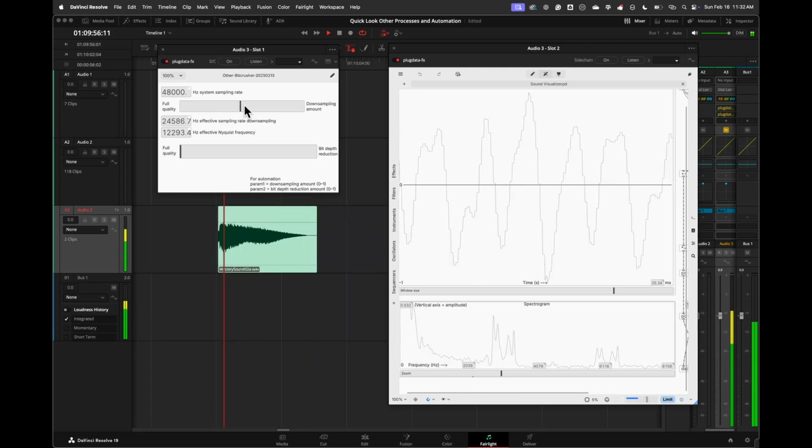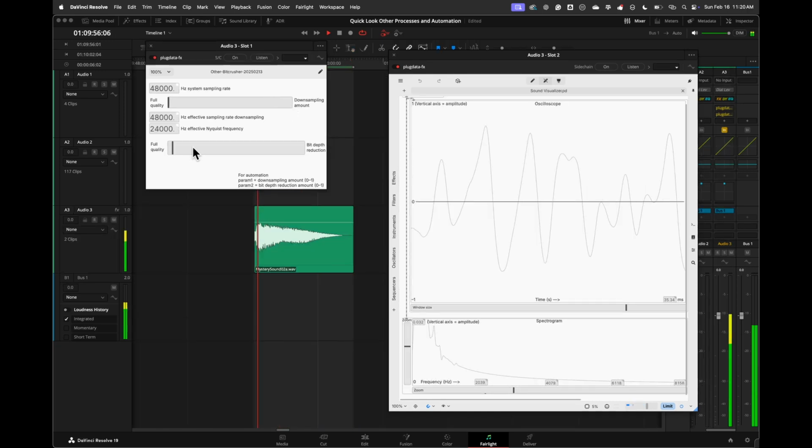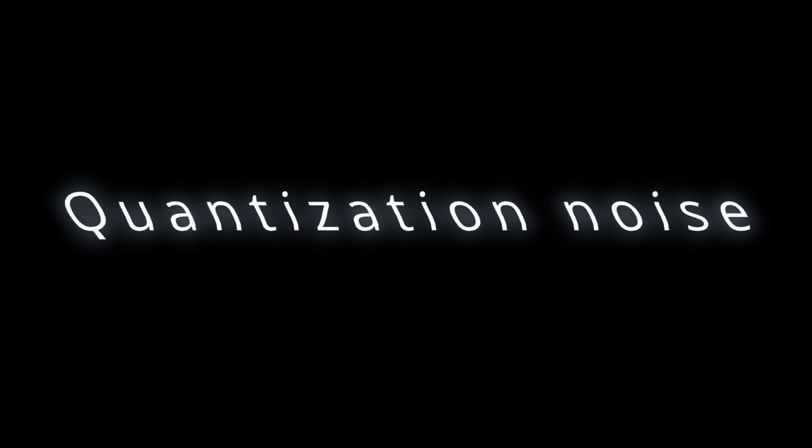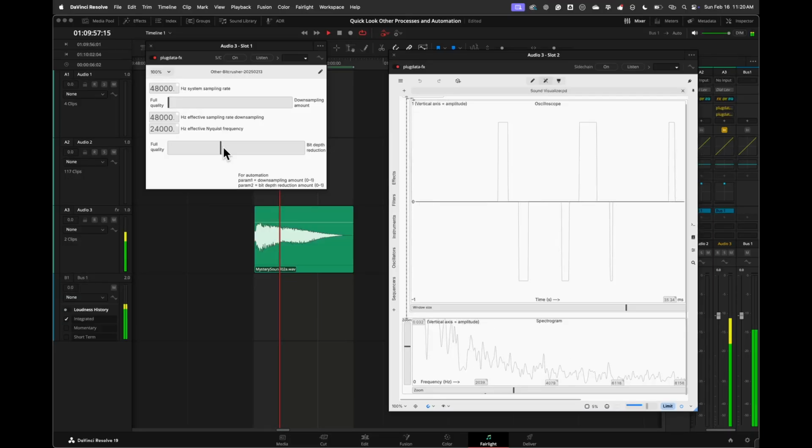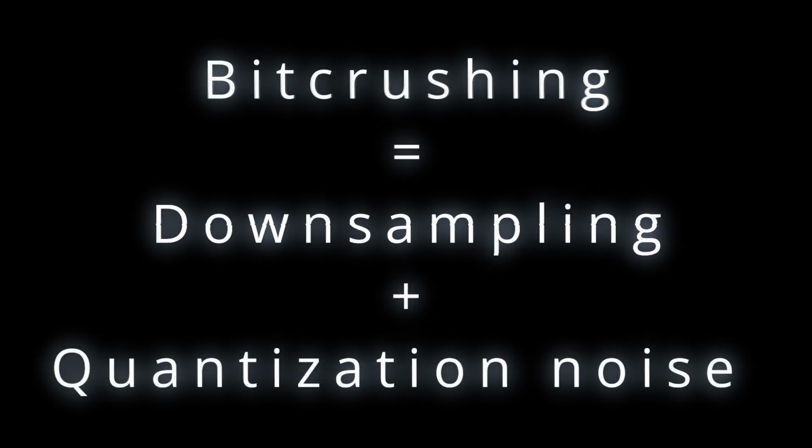At extreme values, you can get parts of the sound seeming to go up in frequency while others are going down, and so more of a squishing effect. If instead of the time dimension, we think of the amplitude dimension, the vertical dimension, we can impose a lower bit depth, which forces our sound to get more jaggies, like in a low-resolution image. Instead of a squishing sound, it tends to be more of bursts of noise, which you also might want to tame with a filter. And so we might call this bit crushing or bit munging.